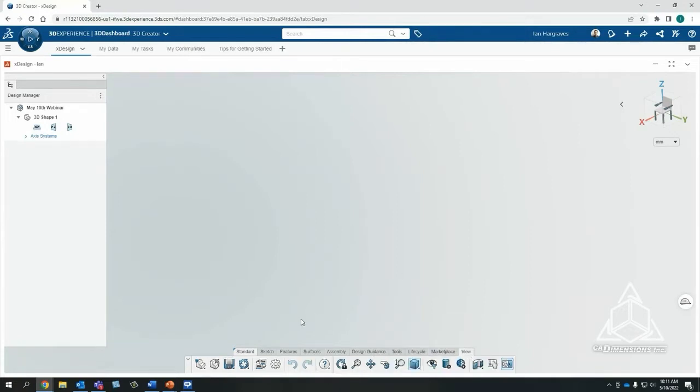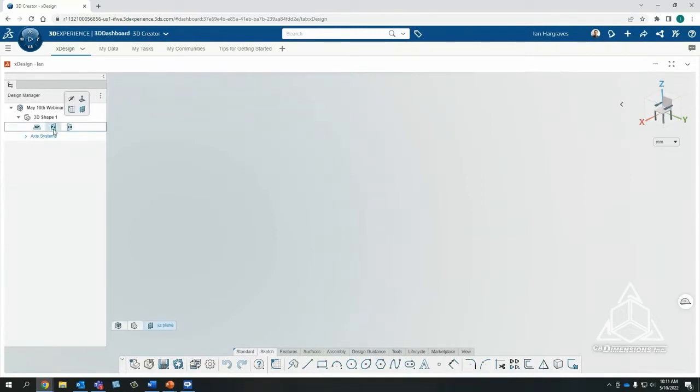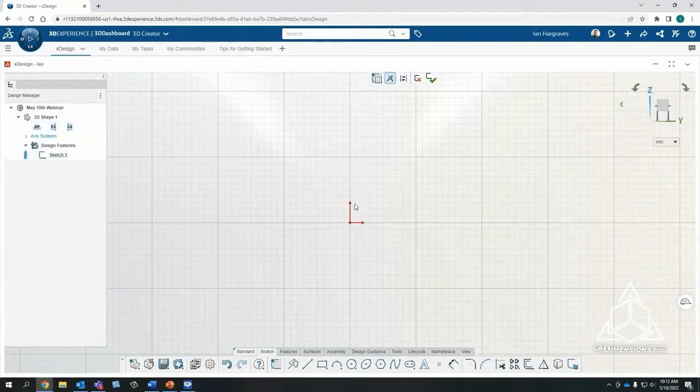All right, so what we're going to do is we're going to start sketching out a model. So just like SolidWorks, I'll go ahead and choose this plane here, and I'll start a new sketch. It automatically normals too. You can turn that off if you'd like, but it's got this grid pattern, and I'm going to start by using a circle. You can notice too that they do have hotkeys. So like for circle, I can hit C to do that. It's all kind of preference.